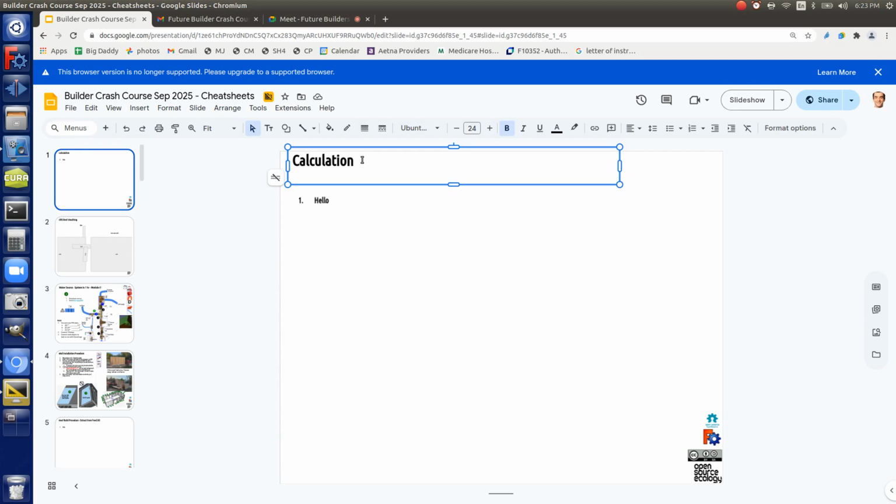Rocks are like concrete. That's definitely 3,000 or 4,000 or 5,000 psi. That's comparable to rock hard, as the cement turns from lime to limestone. So if you talk about rocks and concrete, you're talking a few thousand psi. Now that's stronger than wood, isn't it? Because wood is under 1,000 for practical purposes, unless it's engineered wood, where it's above 1,000. So that's a main quantity you need to consider.